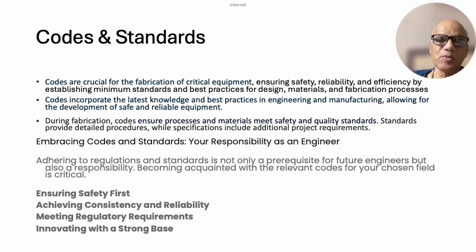So there is a minimum code of what materials normally one can use in structural welding, and how that material behaves strength wise, and what kind of protection is required on these structures, whether you have to give a red oxide, whether you have to do a galvanizing, whether you have to do a powder coating, which is the best method in the given environment.